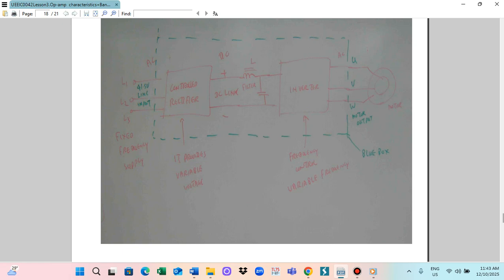And here is the UVW motor output. So we use a 3-phase motor with line voltage 415 volts. The whole blue bulb takes the 415 volt input, and then all the frequency is changed inside the circuit, and the inverter is the frequency control. So on the knob we can change the frequency and supply it to the motor. So this is for the inverter circuit.